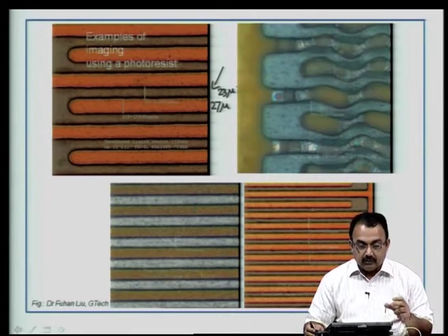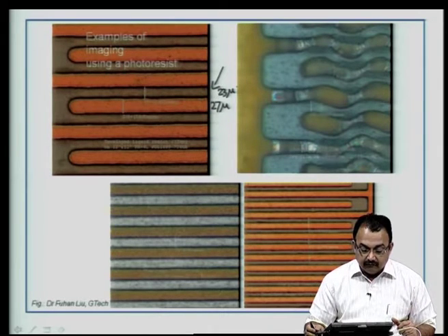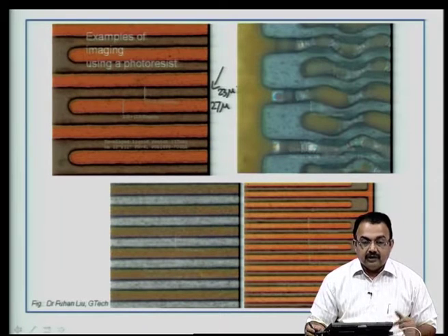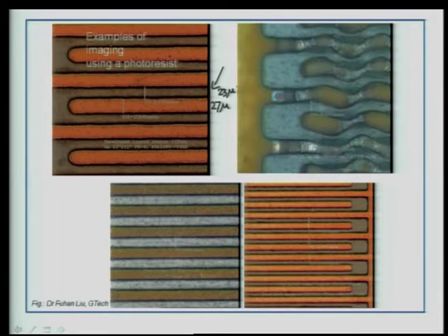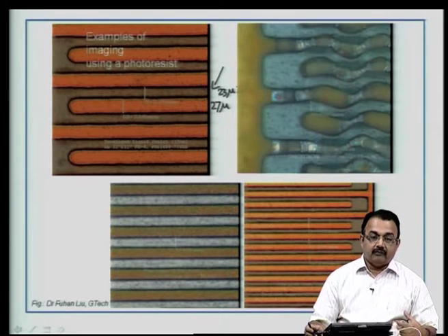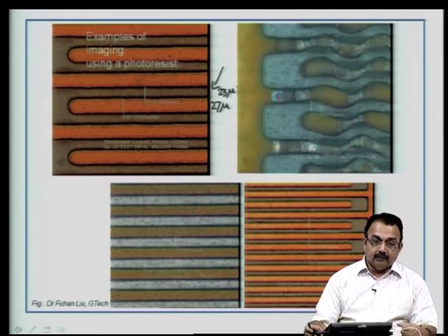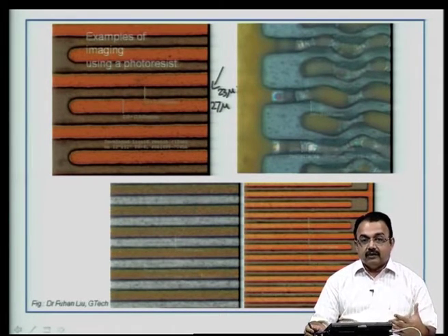This is a zoomed up image of a photoresist imaging process completed with a series of tracks. Copper tracks need to be defined on the board, and you can see that the gap is 23 micron and the track is around 28 micron. So, this kind of resolution is required or expected from the photoresist material. Not all materials will afford this.